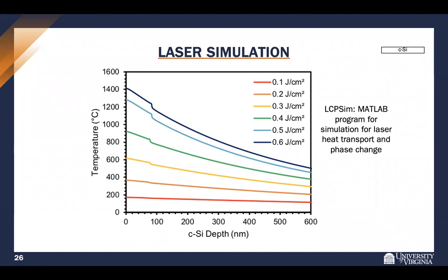This is just for crystalline silicon. A lot of what I'm doing is thin layers on the surface, amorphous silicon or polysilicon. The thermal diffusion in those is much lower. I don't have the numbers in front of me, but it's something like 0.9 for crystalline silicon, in units of watts per centimeter Kelvin, I forget exactly what the units are. But amorphous silicon and polysilicon are in the 0.1 range. So 9 times less.